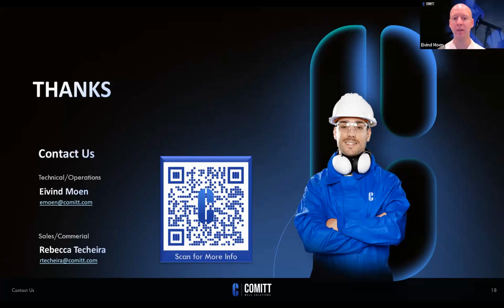Yeah, so the rate you're pumping from surface, if you're straddling, say, 5 clusters, you're not going to know necessarily the rate into each one of those clusters. But if you go down to the individual cluster level, obviously then you're going to know everything. But you're always going to know the rate from surface that you're pumping. Yeah, but if you knew how that rate was being distributed throughout the different clusters, then you could calculate a skin. You've got the pressure. If you knew the rate for each cluster, then you could determine it. But if you're just assuming that it's equal rates, or it's being controlled by pressure, then you could do some diagnostic work. That's all I'm saying.